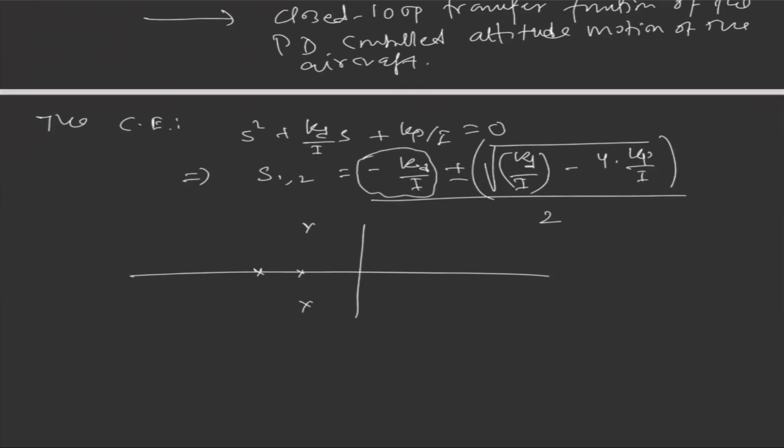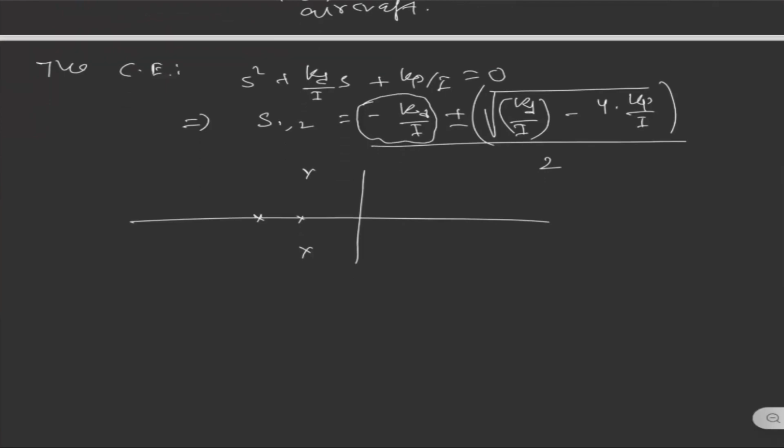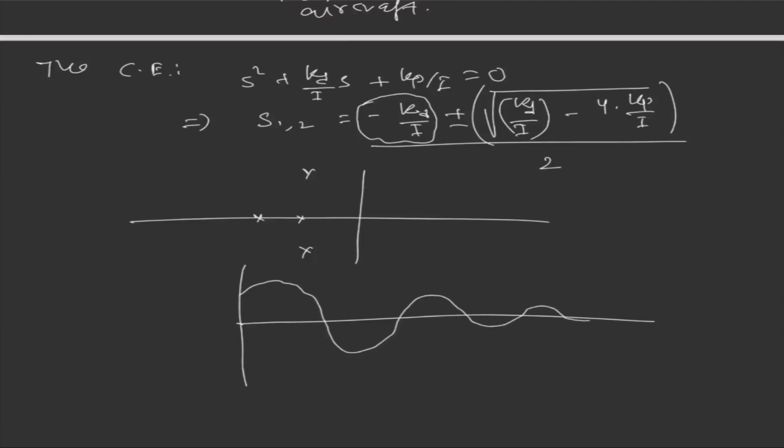So if you solve this equation, we'll have an exponential term in the solution. The system may start with some oscillation, but after some time it will damp out. This is why it is damping out, because of the damping part in the system and because of the negative real part of the poles. This is how we can modify the response that you had in the proportional control.